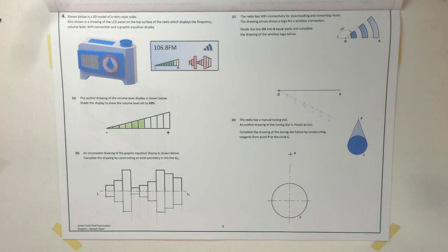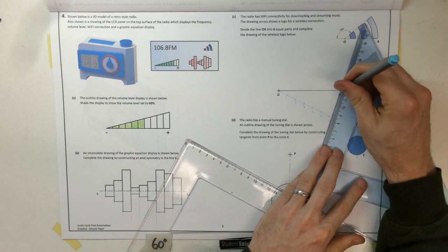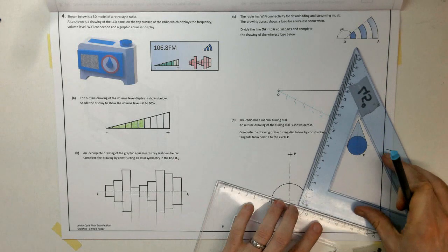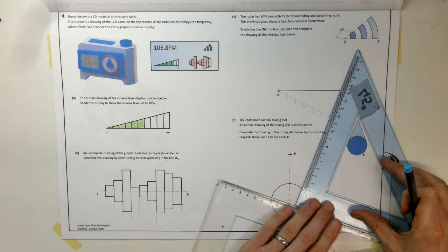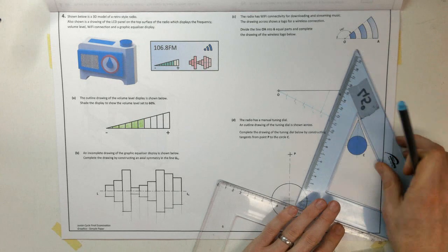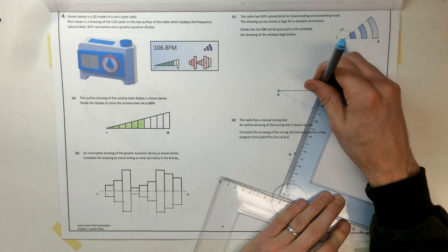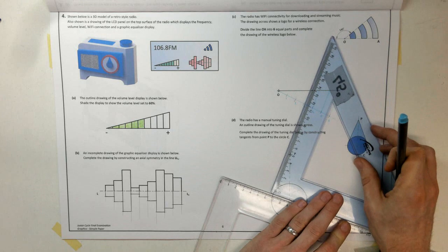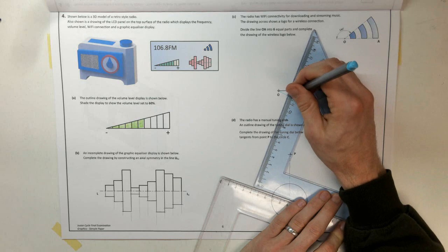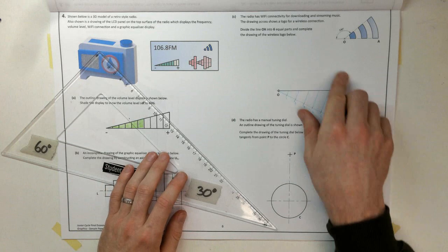Okay, so that done, I want to join the end of my line, so point A back to 6. I'm going to use sliding set squares then to draw a parallel line from 5, 4, that's after moving, sorry, 4, 3, 2, and 1. Okay, so I now know the distances for those arcs that are going to be swung.